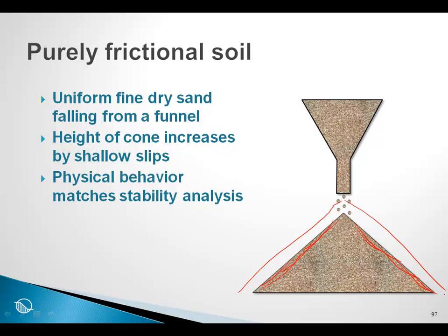You see this also in the field with stockpiling granular material. The height of the pile always increases by slippage on the ground surface. So SLOPE/W, by tending toward the infinite slope case, is actually representing real physical behavior, and matches what's happening in the real physical world.